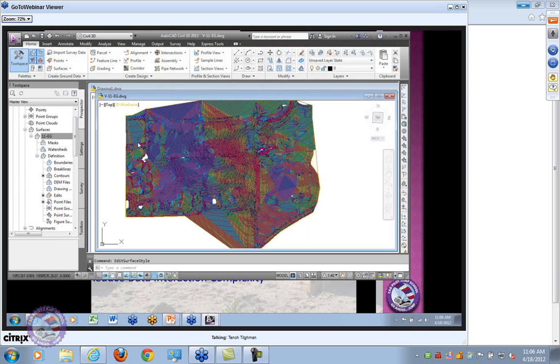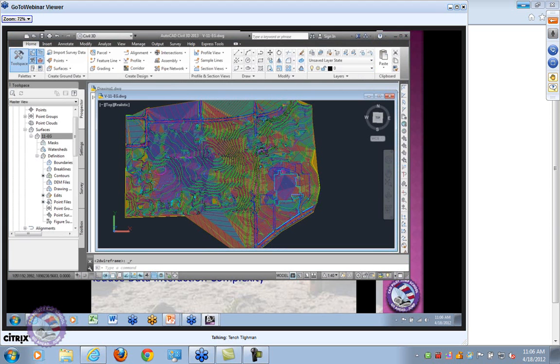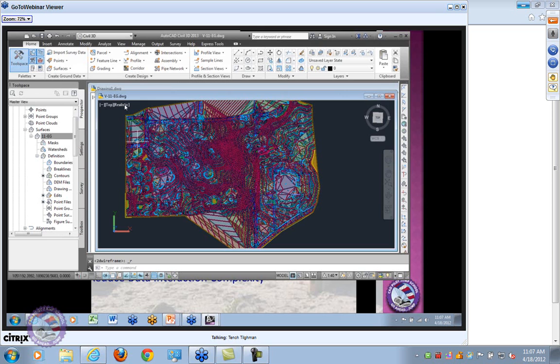So I have Civil 3D style, and I've got 2D wireframe on here. If I make this realistic now, right? AutoCAD itself, which is down underneath Civil 3D, is not even getting involved, but my background changes. Why did my background change? Civil 3D is doing multiple things, and there are some things that Civil 3D is not employing in terms of what we're talking about here, right? Visual style is one of them that, for the most part, it's ignoring.